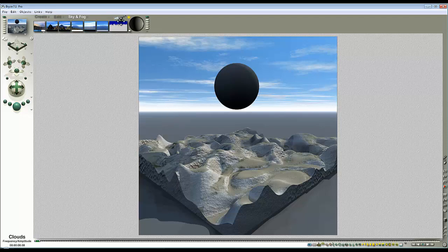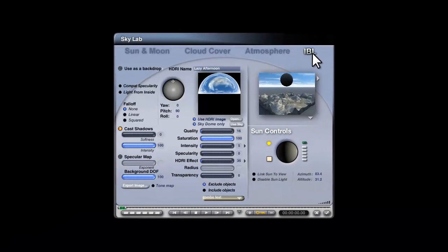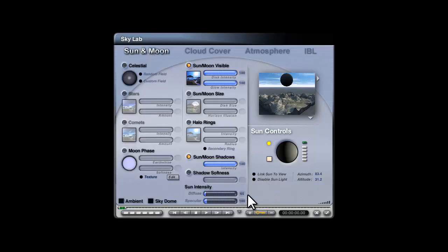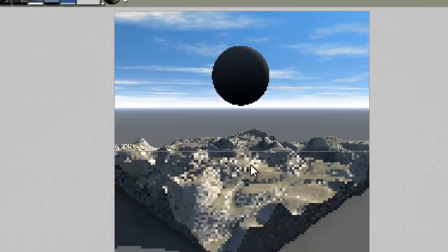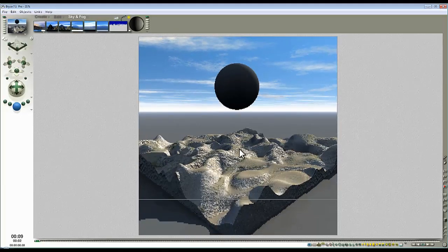So that's quite a lot of blue light. If we wanted more intense shadows, it would be easy to achieve that by reducing this value here, and then compensate for the less light arriving by adding a bit more light on the sunlight side. So you just balance these out to whatever you feel is appropriate. Obviously, as the sunlight gets brighter and brighter, it'll start to burn out the colours coming from the material, which is why you're careful in balancing these out and controlling the shadow regions that you've got here.